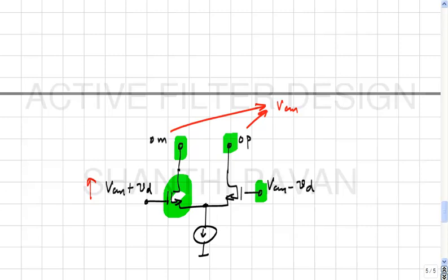The drain can go at the most 1 VT below the gate, but if VD max is the swing at the gate and the drain, what's the worst case? The gate can go 1 VD max above VCM and the drain can go 1 VD max below VCM, correct? So the worst case is 2 VD max, absolutely worst case. In practice, of course, in the filter the phase difference between the drain and the gate need not be 180 degrees. It depends on which node in the filter you're looking at.